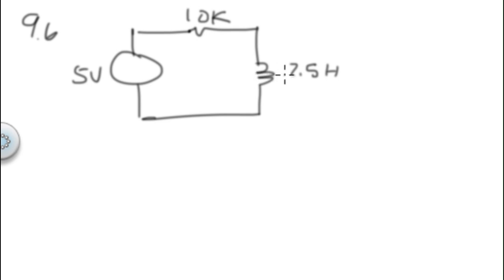And we give a frequency of 100, 500, and 1K. So find the voltage and current at each of these. Basically this one is going to be recalculating the X sub L 3 times. I'm not going to do that for you, but we've done it for one. You can just do it for each of these frequencies, and you're going to see as you go higher in frequency that this gets to be a bigger number and your I goes down. So that's all that we do with that one.